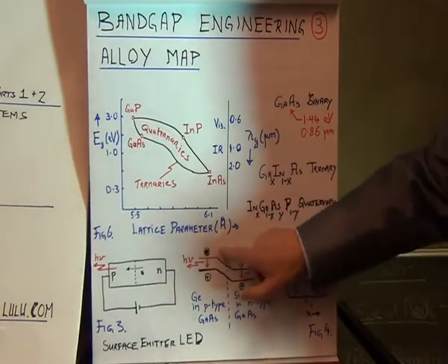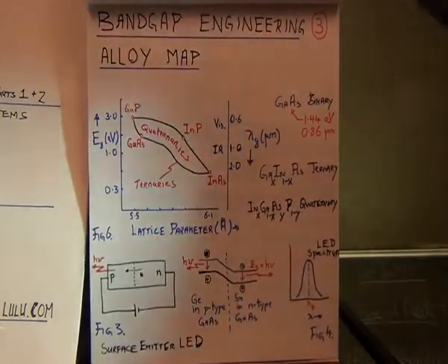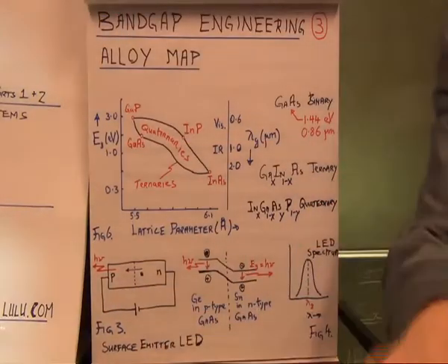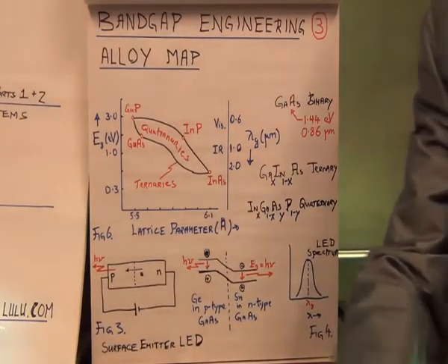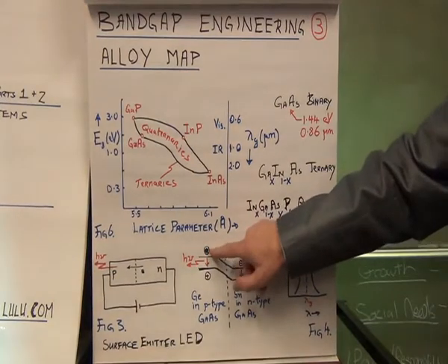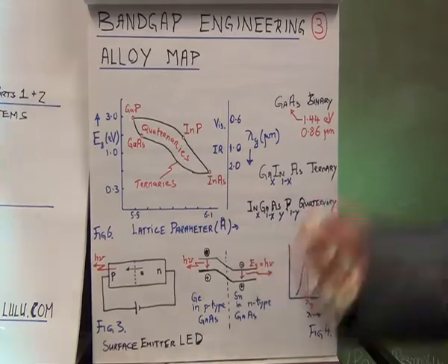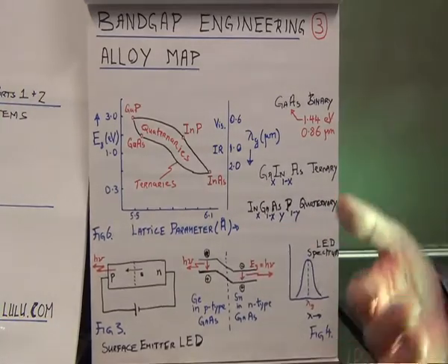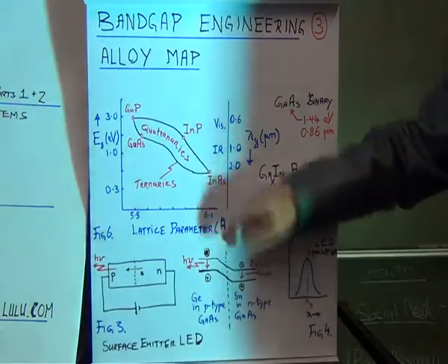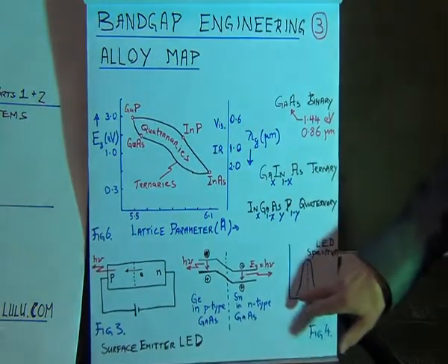Some of the electrons reside a little bit further up. They don't fall down into the bottom of the basin because the bottom of the basin levels might be already filled. So there are some electrons further up. In fact, the spread of energies in the band is kT. k is Boltzmann's constant, and T is 300 Kelvin, room temperature. So there's higher energies, and when they relax back, you get shorter wavelengths.